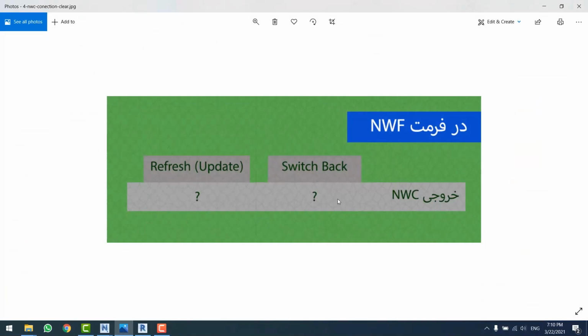And I emphasize that you should use the same versions of Navis and Revit. You should have used equal versions in both software, but it is not required while you want to import your Revit file into Navis. The version does not matter. Well done. Let's talk about refreshing.